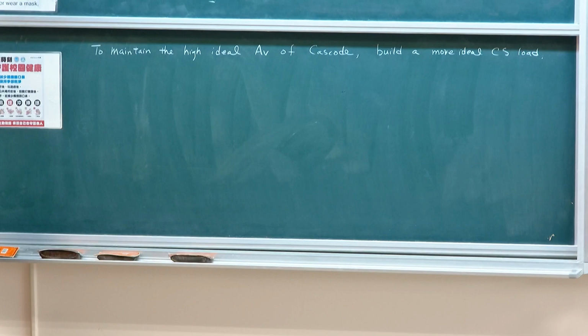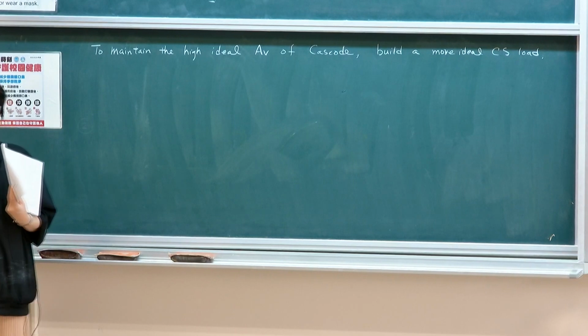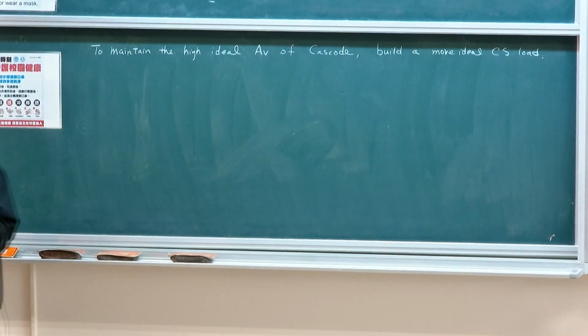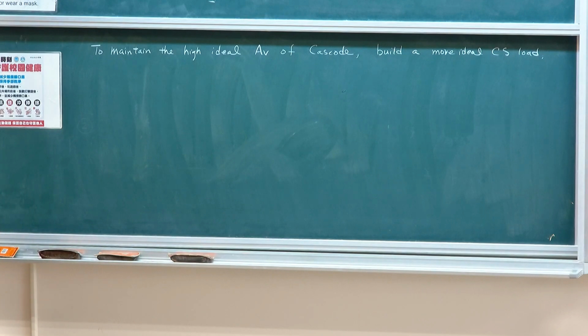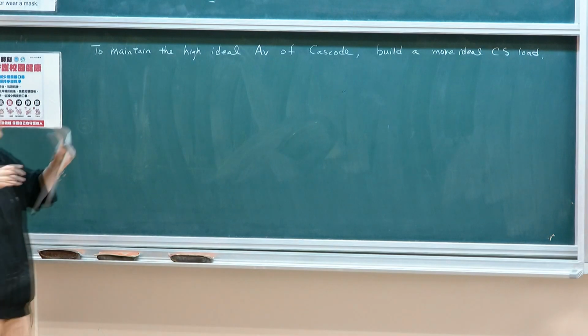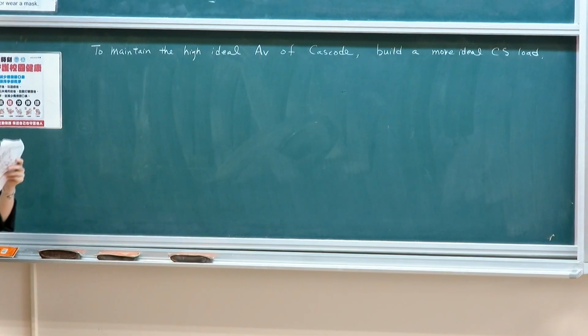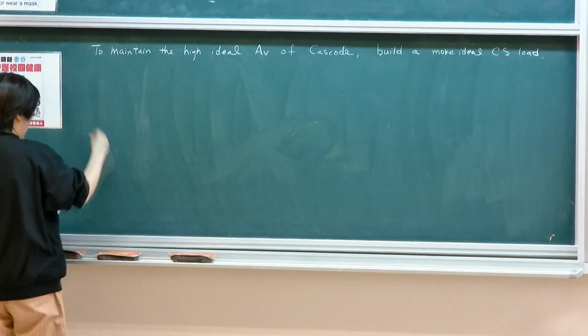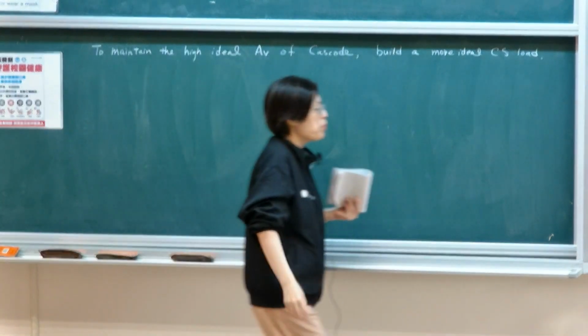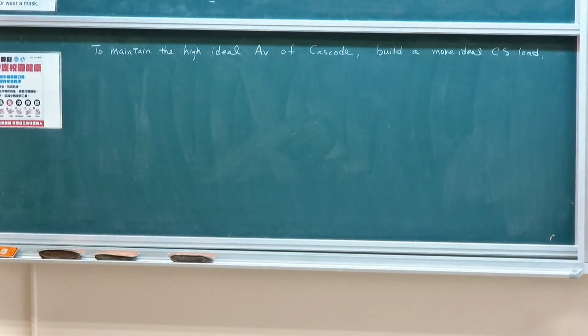It's the same as another analogy: if you do insulation of a house and I only isolate the left and do not isolate the right, then the heat generated will leak out through the weaker spot. It's the same as a resistance. So you need to protect the high impedance node with cascode on both sides. So how does one maintain this high output resistance? The key is to make sure that your output resistance does not degrade drastically.